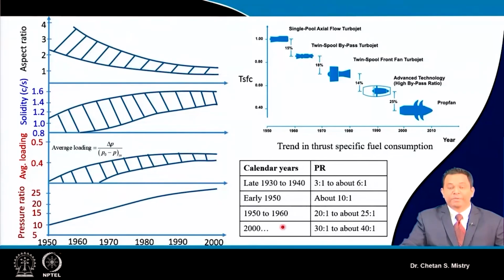So this represents the global trend in the expected pressure rise from the engines. We have discussed that, as of today, with the upcoming engines the maximum pressure ratio has reached above 60. So this represents our global trend in the rise of pressure ratio. Here I am talking about the overall pressure ratio.